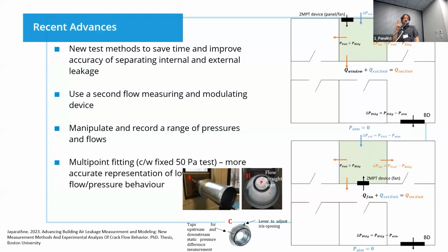And if you can measure a second flow, we had a great discussion earlier today about just using the stack effect and opening some new holes in a building. This is kind of doing the same thing. You're introducing some new holes that you've measured the airflow through. And those techniques look like they have some good promise in terms of getting a much more precise way of measuring all these individual leaks.